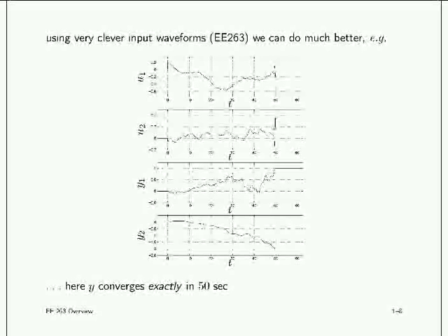So what does this do? If you just shift over 2 centimeters and wait for the thing to stop shaking, you'll wait a long time. If you know what you're doing and you apply an input to the XY stage to move it optimally, the whole throughput on your machine is going to be a whole lot higher.